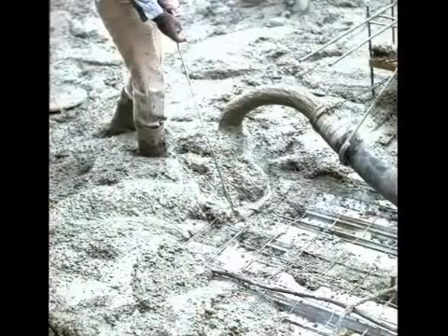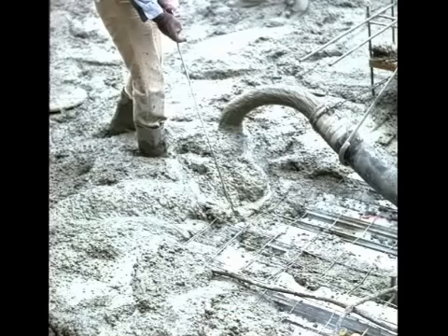Another aspect of welded wire mesh is that it is generally located in the bottom of the slab. Workmen placing concrete are stepping on it and keep it to the bottom. Now, any steel reinforcement that's located on the bottom of a slab provides little in controlling crack size. I generally do not recommend using welded wire mesh.